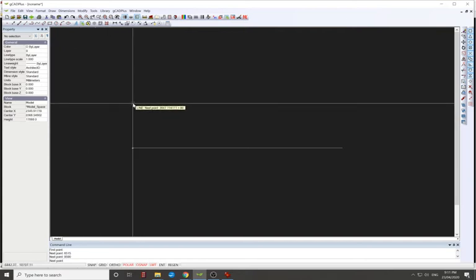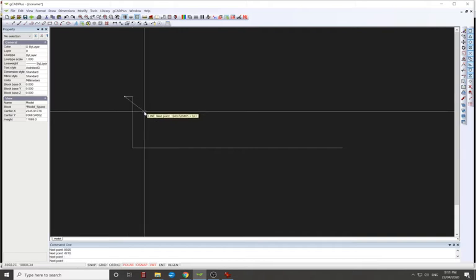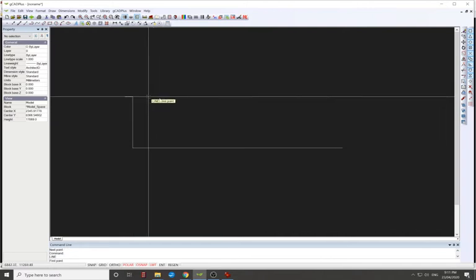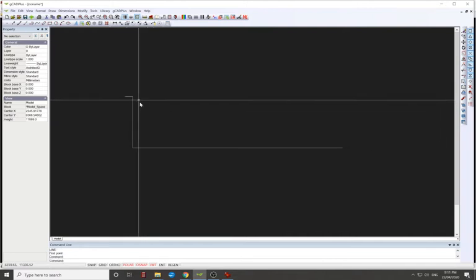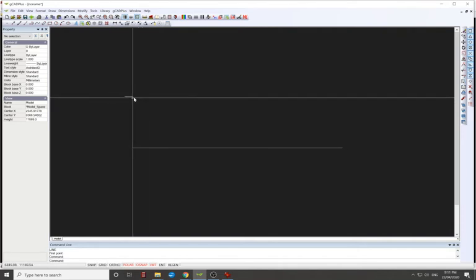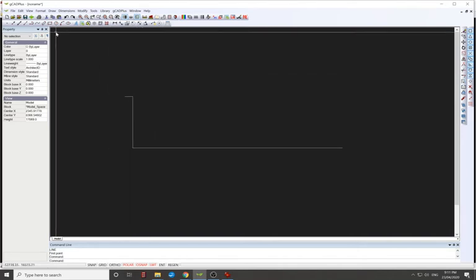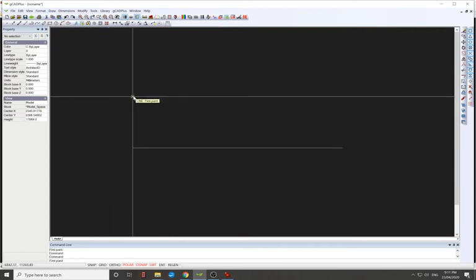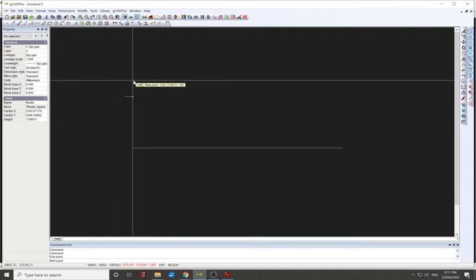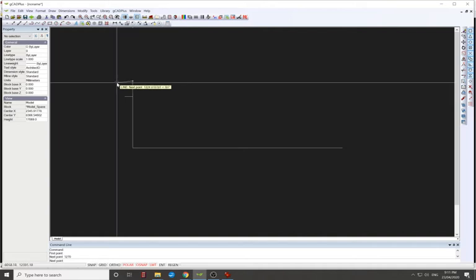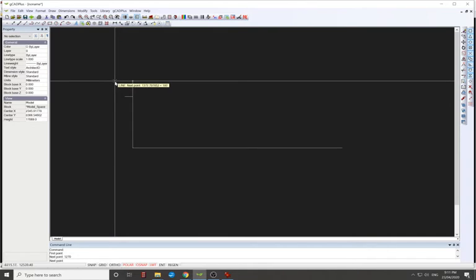The next measurement is 4210. We'll just put a little mark there for reference later, because sometimes I can't find the endpoints or midpoints. In the old Gcad I used to find it a bit easier, but this one less so. It's easy to just move later, and then I just start a fresh line. And this is 1270. The reason I measured that is because that's the same distance on the other side of the alfresco, so I was just trying a bit of symmetry, balanced on each side, but it's probably not going to make much difference once you see the plan done anyway. But at least we tried.